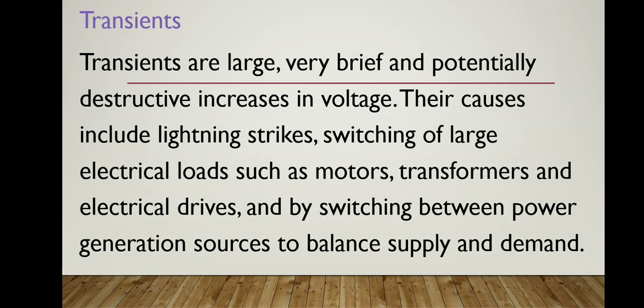Next, transients are large, very brief and potentially destructive increases in voltage. These are caused by lightning strikes, switching of large electrical loads such as motors, transformers and electrical drives, and by switching between power generation sources to balance supply and demand.